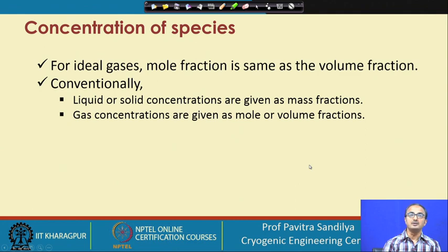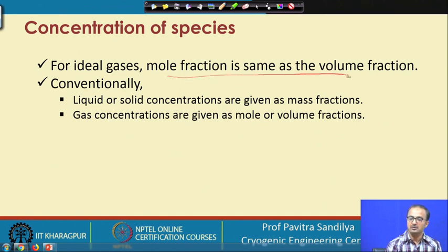The two points are that when we talk of ideal gases, the mole fraction is the same as the volume fraction, and this can be easily proved considering the ideal gas equation of state. And conventionally, the liquid or the solid concentrations are given in terms of the mass fractions, while the gas concentrations are given in terms of the mole or volume fractions. So, if nothing is mentioned in a given problem, we shall go by the convention.